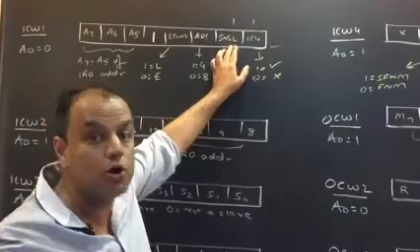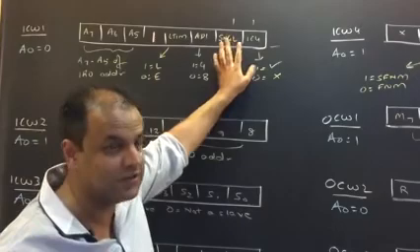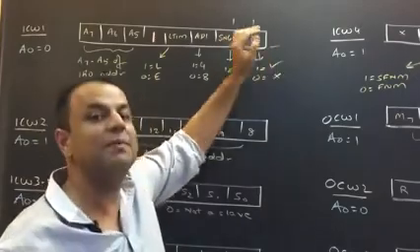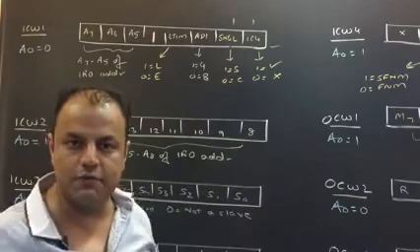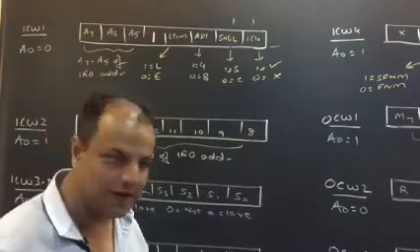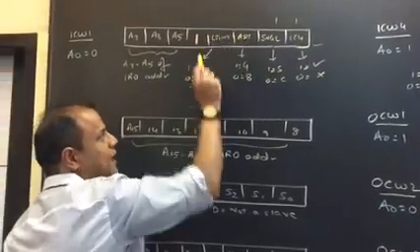That means I am not going to give ICW 3. You understand? It's given only for cascaded. So I am not going to give ICW 3. I've kept this bit 1, that means I am going to give ICW 4. So you're informing 8259 whether it should wait for ICW 3 and 4 or not. Are you clear? We'll come to this bit in a second. Just hold on.